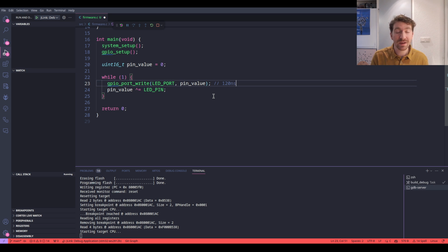I'm not even sure if we could get to that resolution, but even if that was an option for us, it's just way too many interrupts coming into the CPU, stopping it from doing other things. We would never be able to accomplish steady code anywhere else. The systick is much more on a millisecond type resolution, and we're talking about nanoseconds, which is many orders of magnitude smaller than that.